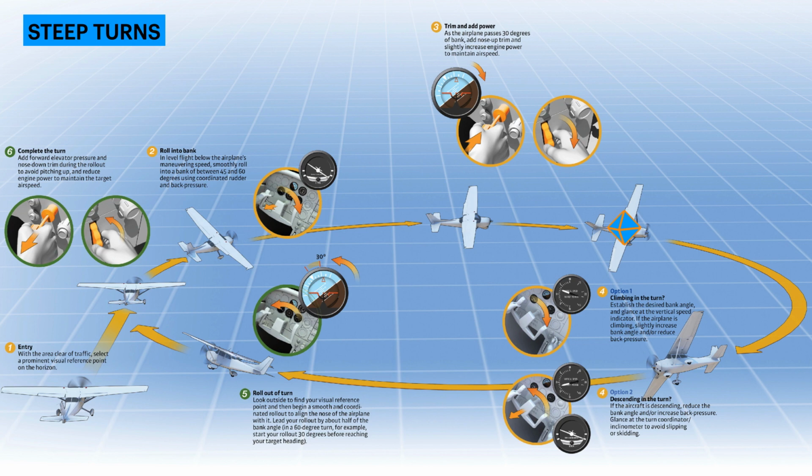Trim is optional. Pick a spot on the cowling or glare shield which you can use to trace the horizon as you turn. Closing one eye can help you keep the reference point and the horizon aligned. Watch for upward or downward deviations of the horizon from your reference point. Remember to spend most of your time looking outside and only glancing inside at the instruments to get the relevant data and return to the visual references.